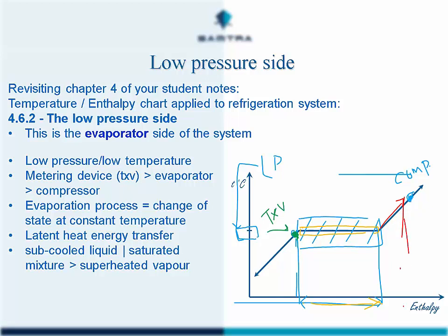And if we just quickly plot down here, we can see that superheat allows us to absorb a little bit more heat energy into the refrigerant. And if we draw a line across there, we can see our superheat value is warmer than the saturation temperature. So we are starting to build an understanding of using the theory and these temperature enthalpy charts to diagnose or to understand the working of a refrigeration system.